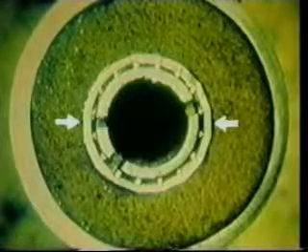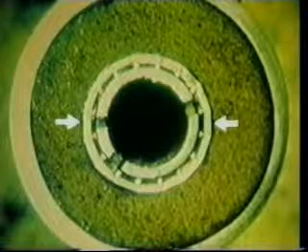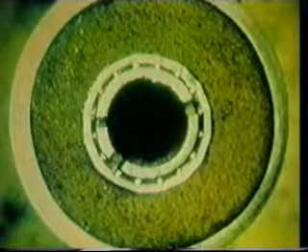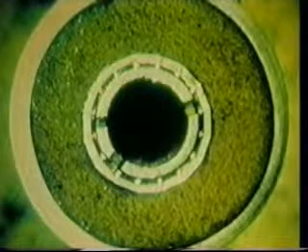The diameter of the screen should be appropriately sized to enable gravel placement in the screen-casing annulus without bridging problems. An annular space of at least 1 inch should be provided around the screen and inside the casing. The tubing and screen are generally the same diameter in single-zone completions. Let's keep these considerations in mind and look at the design of a cased-hole gravel pack.